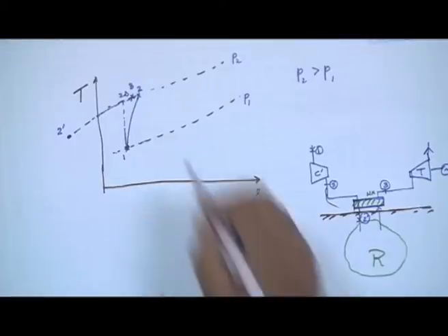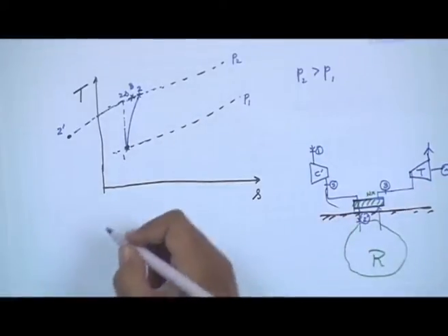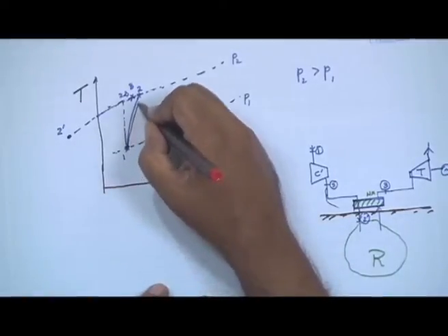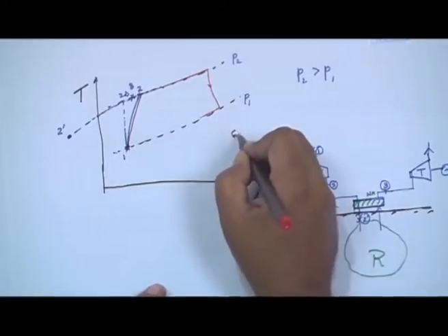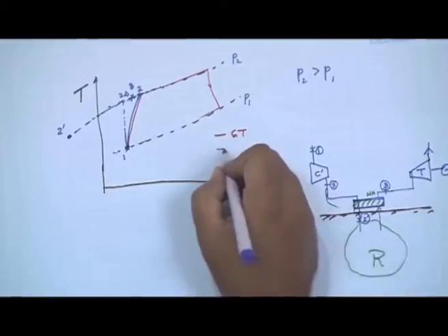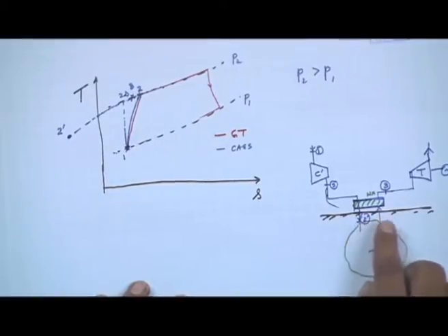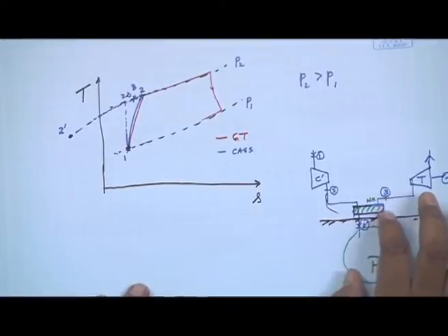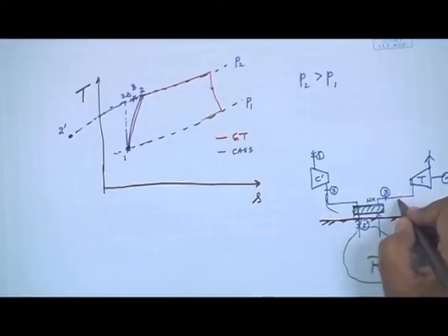Now, the point is that we really do not see that combustion phenomenon that we actually see in a gas turbine cycle, right. If you recall, a gas turbine would have looked something like this. So, this would have been a gas turbine cycle, and this is my compressed air energy storage. Okay. Now, this is a very ideal case where whatever we have put in, we do not add any other energy to the compressed air, we essentially pass it through a regenerative heat exchanger and we get turbine work out. But in reality, we may need to add some combustion over here to increase its temperature further.